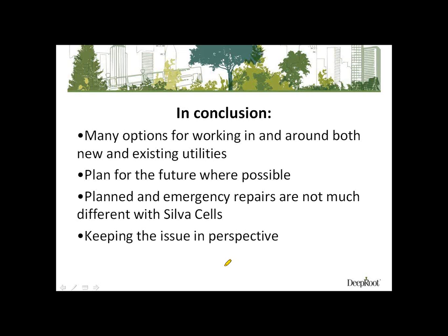No. There's definitely some things you want to pay attention to in the colder climates. If it's going to be installed in the winter, or even when temperatures are getting colder, you want to make sure that you don't get frost underneath the Silva Cells as they're being constructed. It's the same as any civil construction. I keep frost out from underneath the foundation while it's being built, things like that.